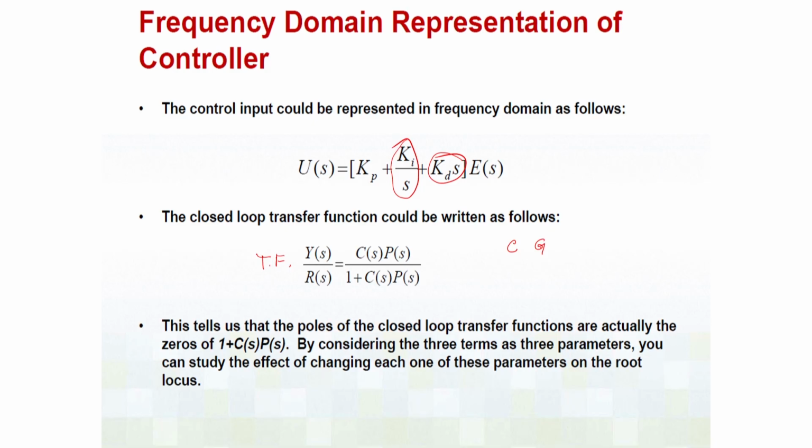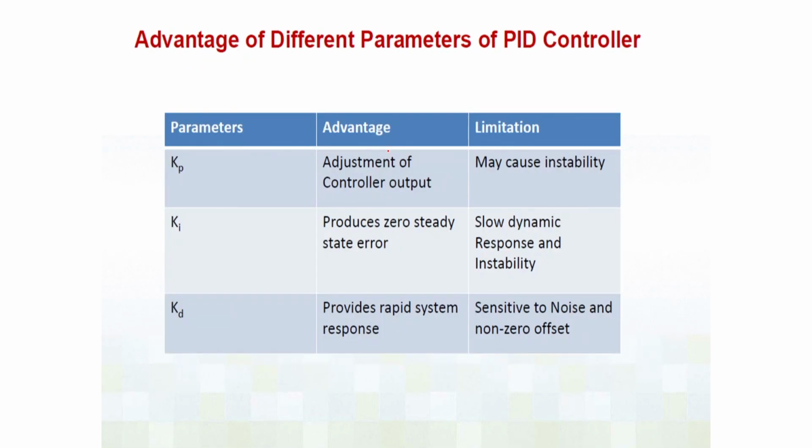Okay. This is corresponding to of course unity gain in the system, and then over R(s). So, this will become C(s)G(s) over 1 plus C(s)G(s). Okay. So, something like that will come up. Now, this is the transfer function of the system where I can use for the C(s) transfer function this one that we already know. So, I can use this system.